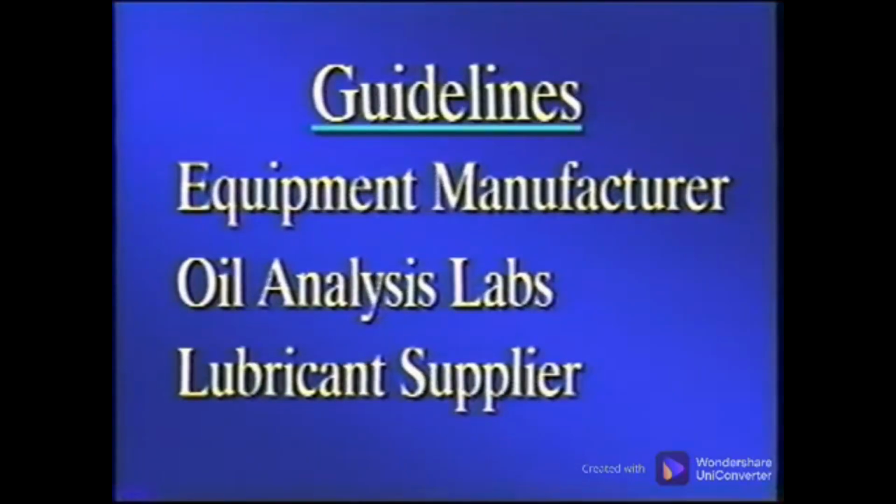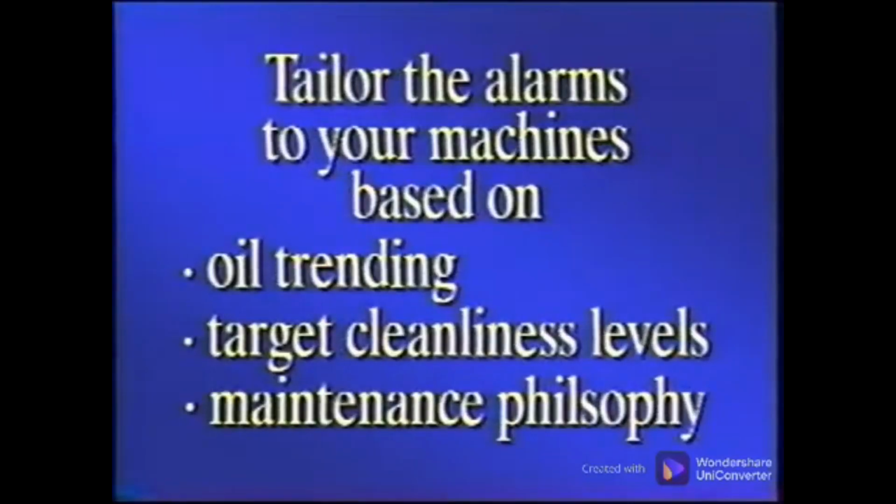Standard machinery guidelines are usually provided by the original equipment manufacturer, the oil analysis laboratories, and the lubricant supplier. These sources provide good starting guidelines, but just like vibration alarm levels, they must be tailored to the machine based on oil trending, target cleanliness levels and the maintenance philosophy of your plant.